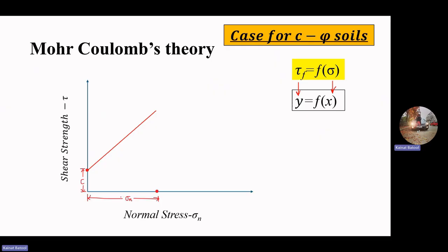Now what we will do is translate these two parameters onto the next axis. Sigma n translated above, and again C translated laterally. Now what will I do? I'll join this point to the point on the x-axis. So we can calculate this total amount of tau f. There you go. Now you can see this is a right-angled triangle, and we have a value for the base.